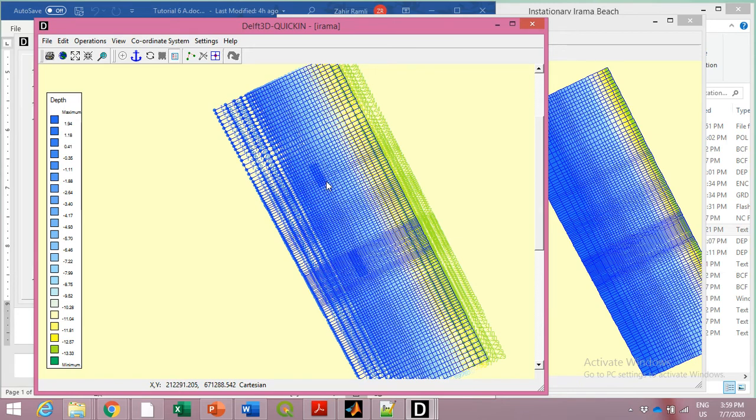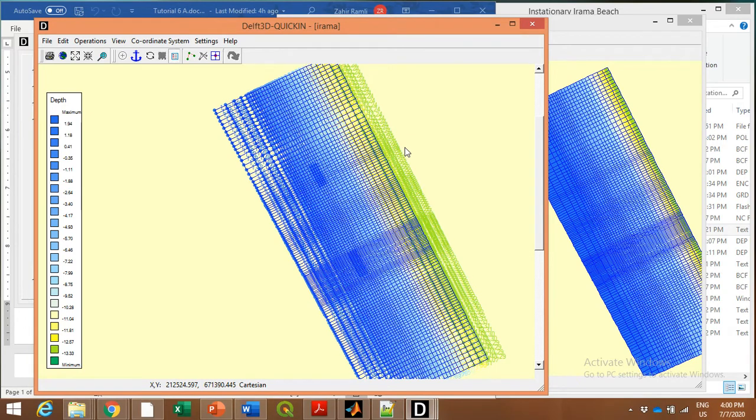And by changing the depth file, it actually creates two breakwaters. But in order to make sure that the breakwater is considered as a structure, you need to add the non-erodable layer. Okay, that one, we go to the next question.